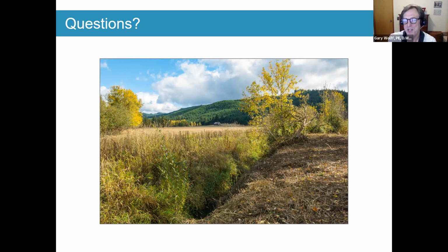So typically what we should know about the geotechnical, and you're absolutely right that we should be working very closely with the other disciplines, with the geotechs and the structural folks. And if we've got bedrock, we want to know that because that may limit the scour. And if it's competent bedrock, that's great because that's going to limit the scour depths.